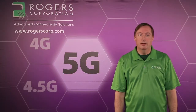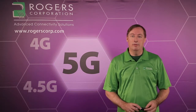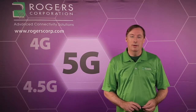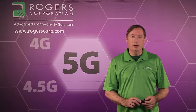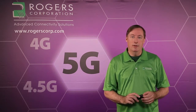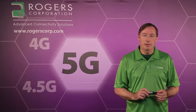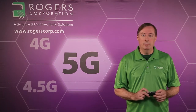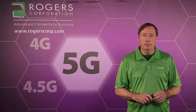There are other aspects that can impact the phase performance of the circuit as well, and one of them is called TCDK. TCDK is an abbreviation for thermal coefficient of dielectric constant, and that's a property that unfortunately is often overlooked. It can cause problems when a circuit or an assembly is optimized in a controlled environment, and then it goes out in the field and goes through temperature swings. Every material has this property where the dielectric constant will change with the change in temperature. That's something that needs to be well understood for many applications at millimeter wave frequencies.